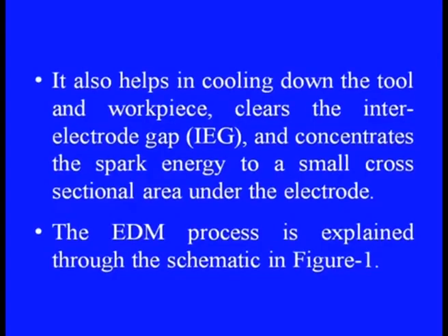The dielectric fluid may be a typical hydrocarbon oil, as we have already indicated. Usually kerosene is preferred, or at times deionized water is also used. It also helps in cooling down the tool and the workpiece. It clears the inter-electrode gap and concentrates the spark energy to a small cross sectional area under the electrode.